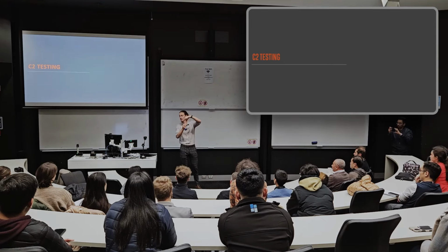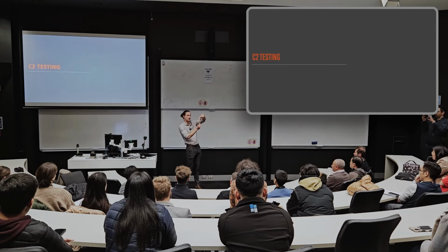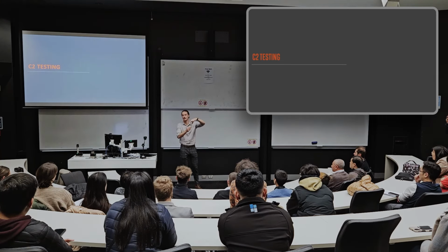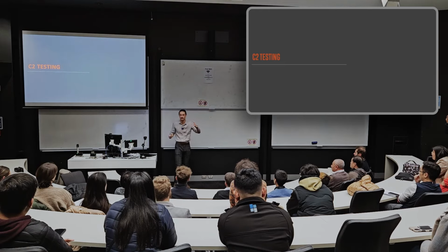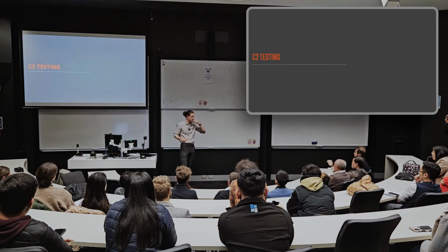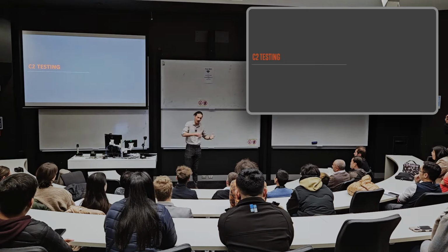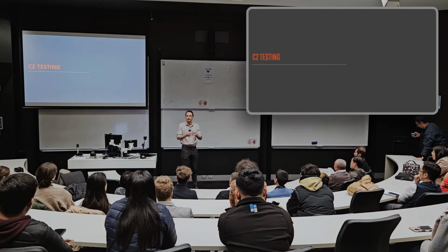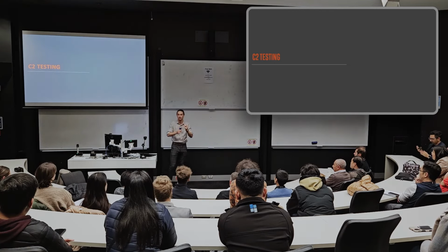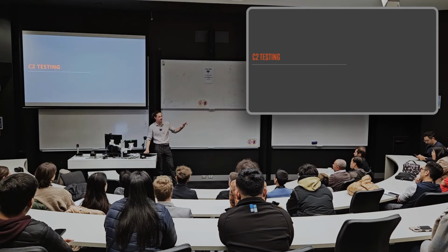When the cracks occur where the anchor is, take it to an extreme example, your anchor is going to fall out. But those moderate examples do impact anchor performance as well. The larger the crack, the less capacity that anchor is going to have, fundamentally. The other aspect of seismic loading is, of course, what the anchor actually experiences. And so these are those loading protocols on the anchor, and that, broadly speaking, is what C2 is trying to capture.